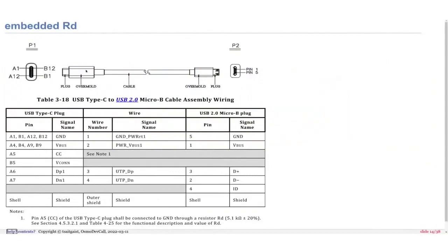What's also fun is this kind of cable, they exist. On one side, you have USB-C. On the other side, for example, you have micro USB. You could have also mini USB. They also exist, or just plain USB, USB-B, which is normally connected to the device, like printers and things like that. And if you look at the node 1, on the CC line, there is already a resistor embedded in the cable. So the 5.1 kilo ohm resistor, Rd, is embedded in the cable.